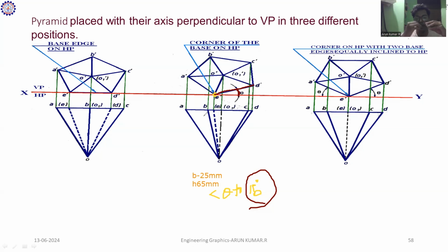What we do is take the interior angle from this point. What is the interior angle of the pentagon? 108 and 108. So you mark 108 degrees over here. That point is called A dash and C dash. From these points, you take an arc of 25 mm, cutting from A dash and C dash. The two arcs meet at one point, called B dash. That B dash completes the whole pentagon.